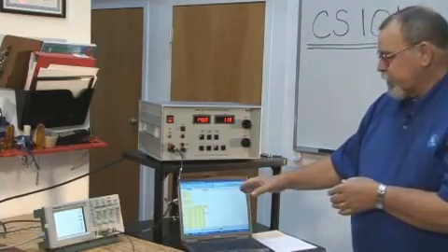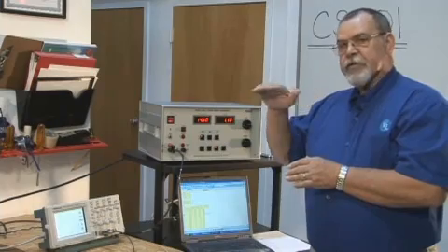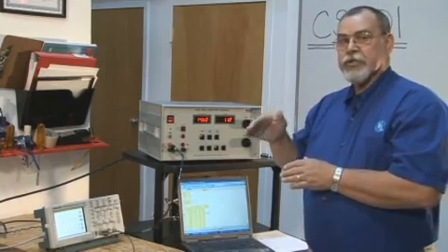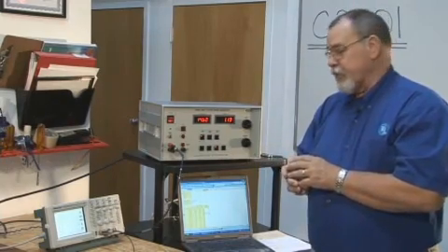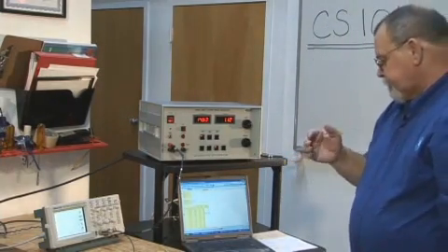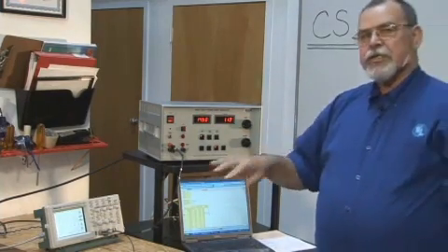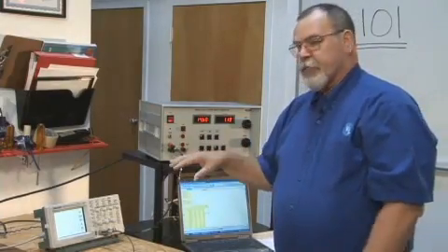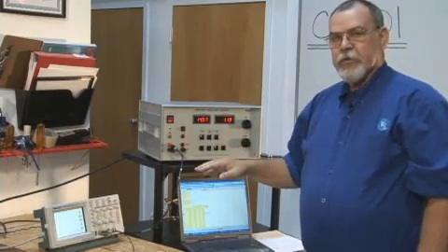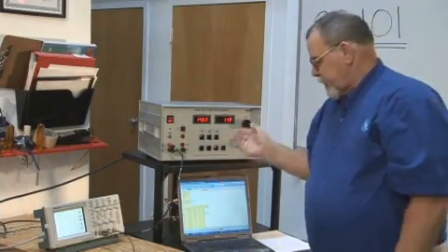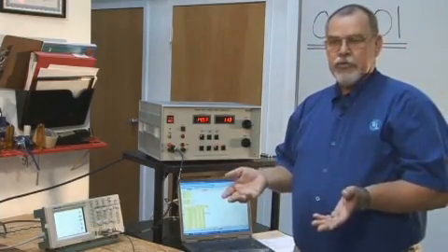We've recorded all of our numbers. Now note, when we get to 5 kilohertz, the power limit starts taking a curve to where it starts decreasing. So we'll have to be much more attentive to how far we are above the level. So let us realize that now I have these points already determined. Once I get this complete set of data for the pre-calibration, I know what the voltmeter setting is for the maximum power. With this, once we've recorded all these numbers, we're ready to proceed with the testing. So let us go towards the testing at this point.